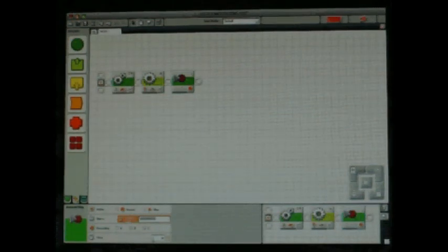And then you set a time duration. And during that time duration, the robot will be expecting you to move the motors by yourself, and it will then mimic those back when you select play. Notice play, it grays out everything, but it does have down here file, so you can pick different files. So like if you recorded move 1, and then move 2, and then move 3, well, you could play those back in any order through the file selection.